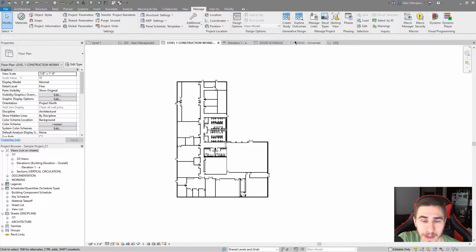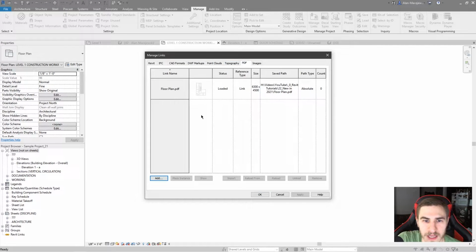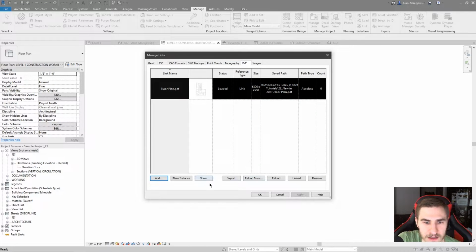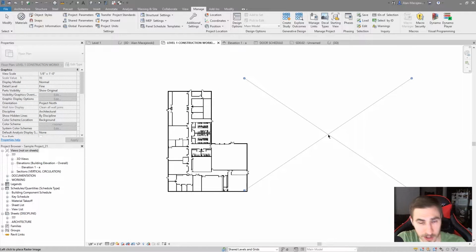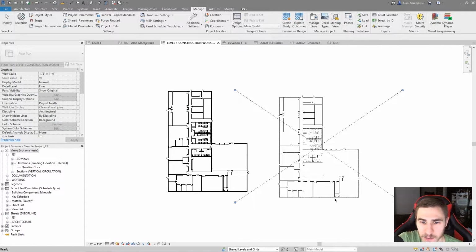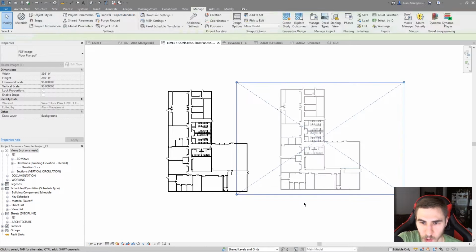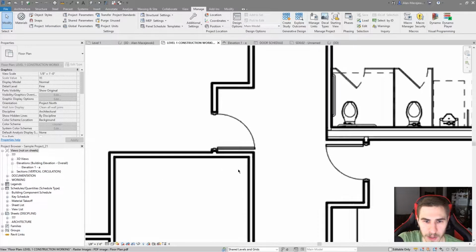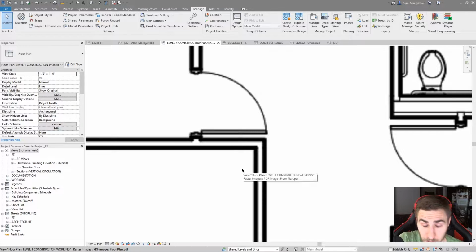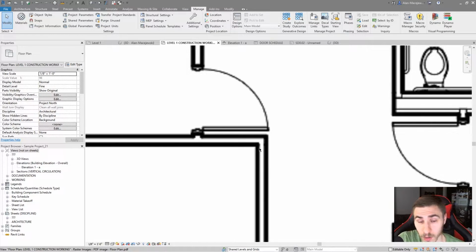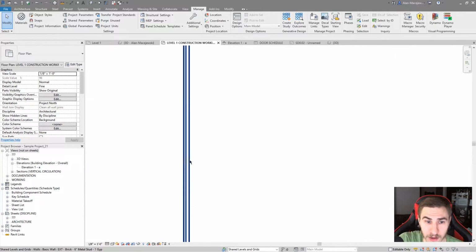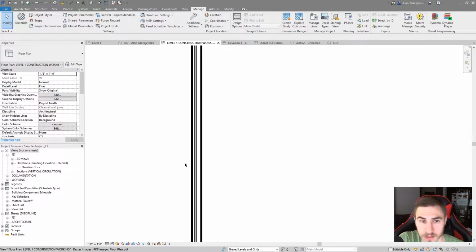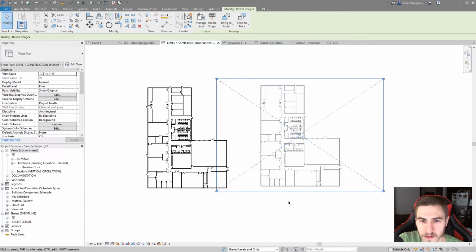So now, maybe I want to place this. Well, I can go back here, of course, and I can go to PDF and click on it, and there's Place Instance. So I can actually choose this, and it's going to just go to the view that you're currently in, and I can place this. And look at that. It works. I can see my PDF. And we can clearly see that it's rastered because it's blurry, and as I zoom in more, it gets more blurry because I set that 150 dpi, compared to my rasterized Revit, which, you know, there's a clear difference, obviously, because this is a PDF.